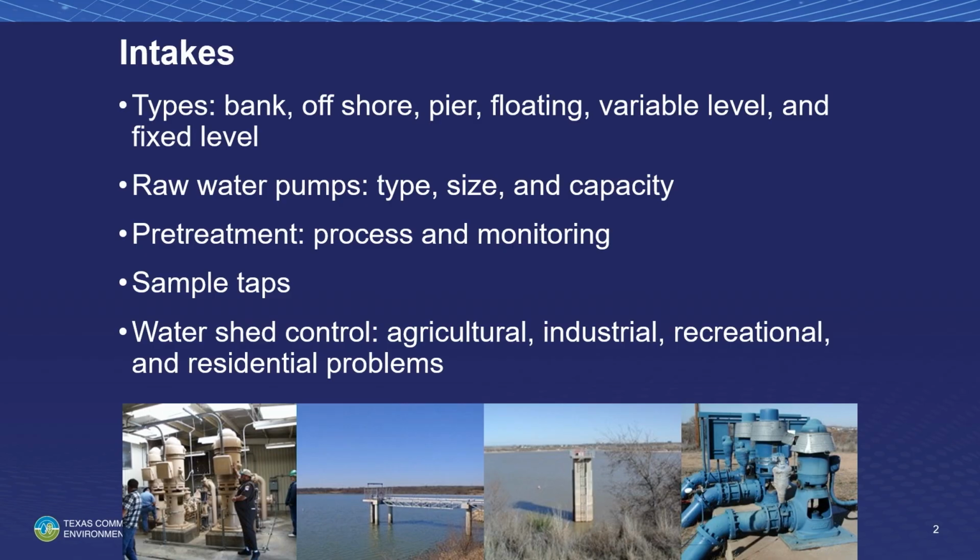Sometimes we do treatment at the raw water intake. Quite often it's an oxidant of some sort, a pre-treatment with chlorine dioxide, sometimes something like permanganate. And you have to be particularly careful, particularly if you're treating for manganese, and you have to raise the pH to make the chemical reaction happen.